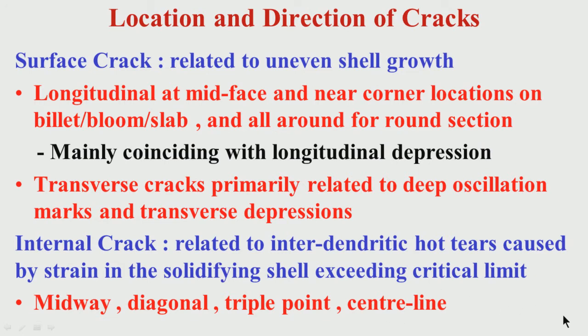So now what you can do in the normal circumstances, you cannot avoid center line segregation and crack. The only thing you can do is control the undesirable elements like sulfur and phosphorus, so that you can have less amount of central segregation, less depression of the solidus temperature. And you can use low superheat casting, so that you can have more equiaxed zone at the center. So these cracks and segregations get distributed and do not concentrate at the center line.